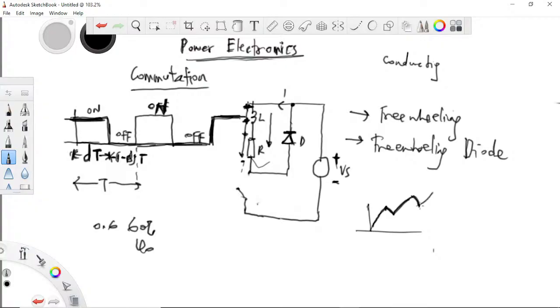This happens until we reach a steady state where the waveform is periodic, like the peak and the trough are the same. Initially, in the build up state, the inductor builds current, not to its highest level. Then as it's discharging, the switch comes on again, so it picks up the current and goes up.